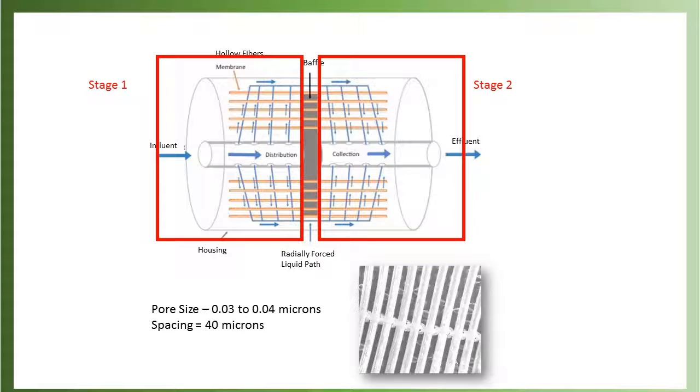We have run this system, in fact, we have a patent on looking at oil-water separation with this contactor. And we have separated produced waters, frac waters, and in fact, the original work where we used this was a project looking at trying to extract oil from algae. And so we would take the algae, burst them open, right? So we break them open, and then once we break them open, we have all the algae parts. So now you have like algae mess, and you put it directly into this contactor,